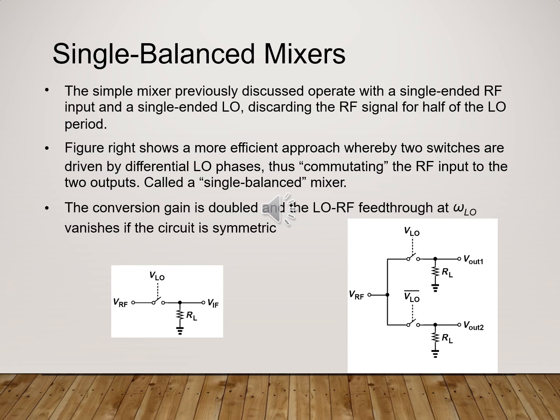We discussed that we can make a mixer by just using one transistor or one diode, but this faces a lot of challenges with port-to-port feed-through, as we explained before. So with single balanced mixers, we provide isolation between the local oscillator and RF inputs as shown in the right figures.